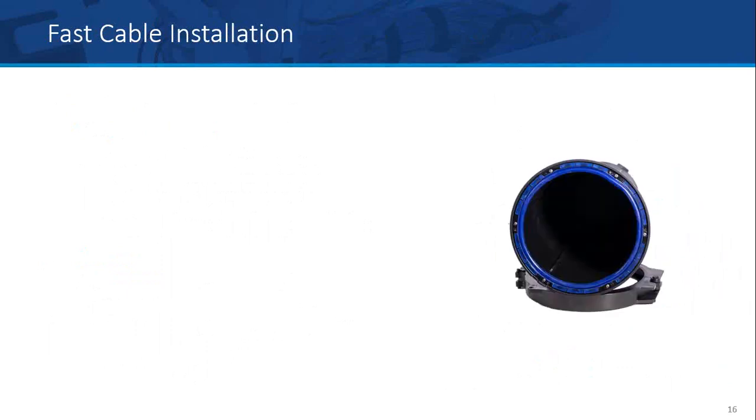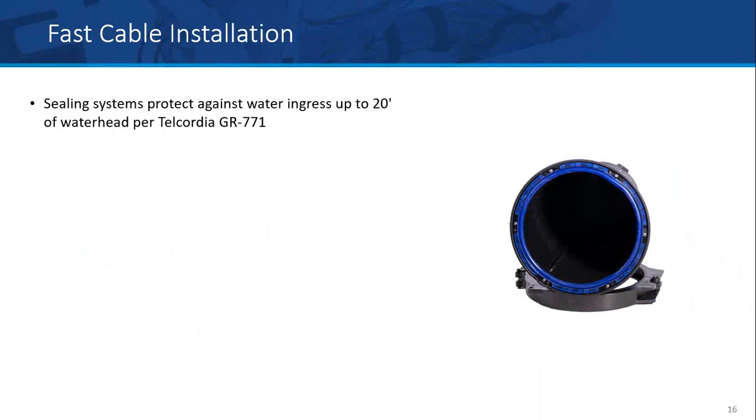You also have the O-ring. The O-ring in the splice closure is really a very important piece of the closure. So overall, from a cable installation perspective, what is the splice closure doing? It's protecting the fiber splices in the outside plant environment from the elements, everything from weathering to impacts and extrinsic forces from things falling on it, insects, squirrels, you name it.